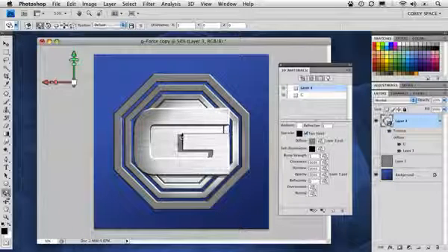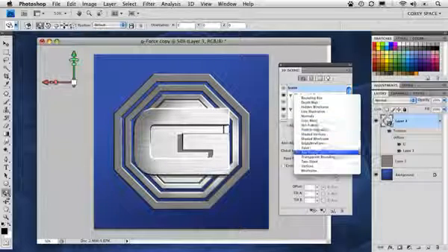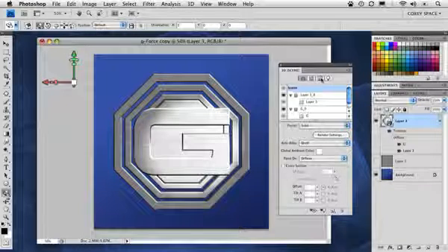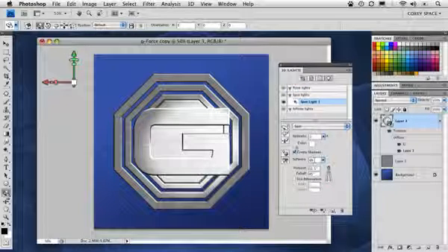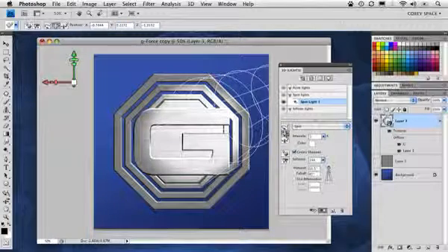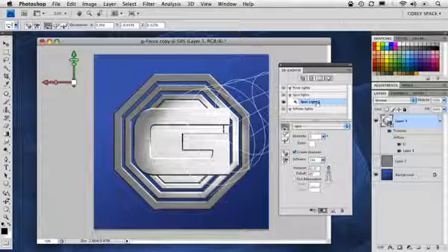So you can see that shadow is a little bit harsh. So if you decide you want to soften that up, you can always go back inside the lighting section. In fact, to make this quicker, let's go back into solid mode because I think I want to reposition that light too. Go back into the light section, and here in the softness area, let's enter 15 for the softness. And let's turn on that light wireframe. And let's just position this up. I'm going to slide the light up here a little bit. And push that direction down, just so it's casting more of a shadow on there.